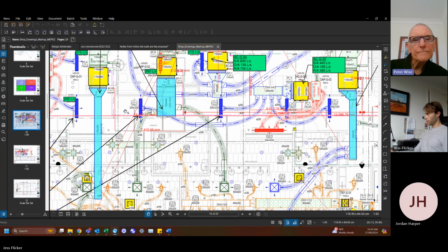Well, anyway, that's another option, but to have a special outdoor air conditioning unit to precondition outside air is fine, but it's probably a bigger cost to install and to run than an ERV. And in actual fact, what was the airflow rate for those fan coil units?